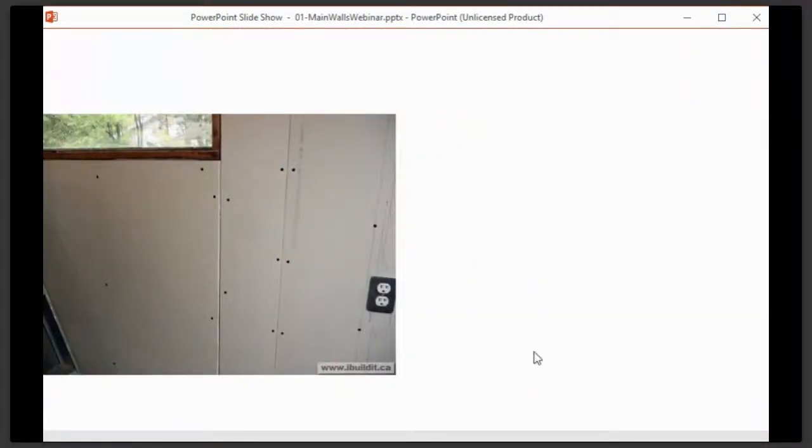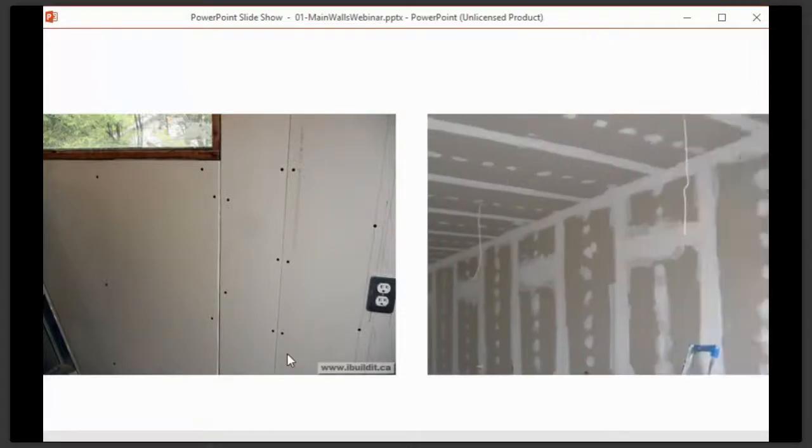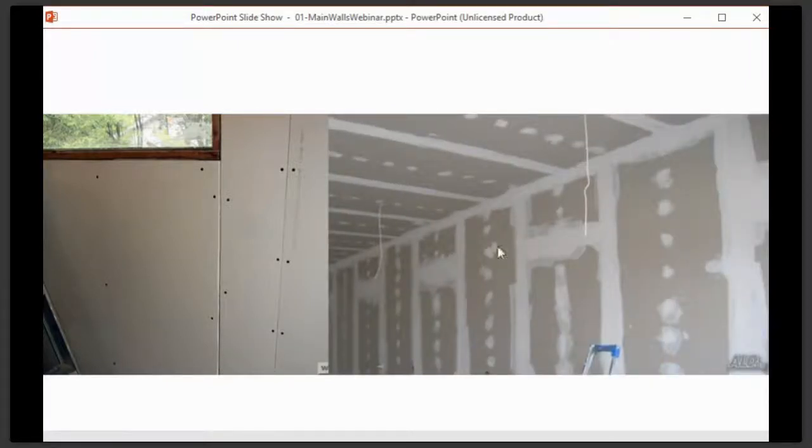Once the plasterboard is on, this is plasterboard that's been screwed in place. You've got all these different size sheets. They're one size, and you cut them to size literally to fit the wall space. They're butted up against each other, but at the same time, it's still quite an uneven surface. So what they need to do is finish it off and make sure that the whole thing is smooth and completely level. They'll pull through the wires, pull through any pipes, etc., and make sure that there's access to them.